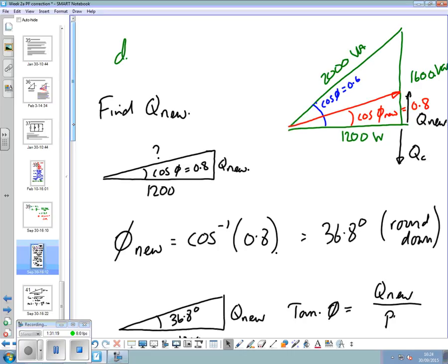If you made this line longer than that one, then you'd draw S down underneath here, and you'd have an overall capacitive circuit. And you don't want that either, because again you're going to start drawing more current. You're going to end up with a phase angle. So there's a balance to be made, and they usually try and get it around 0.8, I think, somewhere between 0.8 and 0.9.